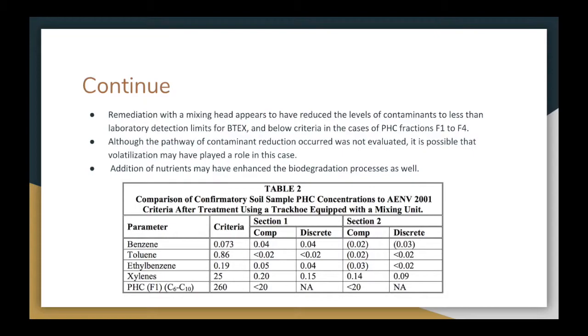All analyzed parameters, except for the electrical conductivity, were below criteria. This factor may be related to the high solubility of nitrogen fertilizer that was added at the time of the remediation program. EC levels were about 2.9 dS/m in the confirmatory samples. Although it is above criteria, transformation of nitrogen ion to organic matter and leaching due to rain events may reduce EC levels.